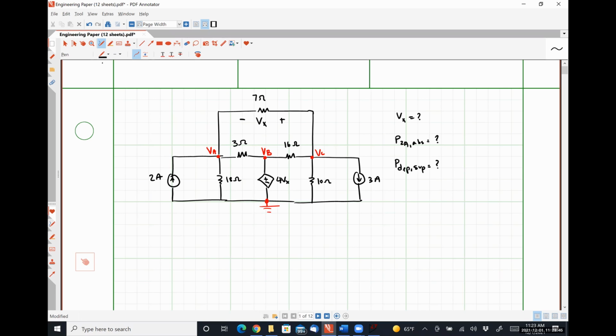Because this circuit has a voltage source, it contains a supernode. The supernode will be between node B and ground. So we will only have a voltage relationship expression. We will not have to do Kirchhoff's current law, because we never do Kirchhoff's current law at a node or supernode that contains our reference.